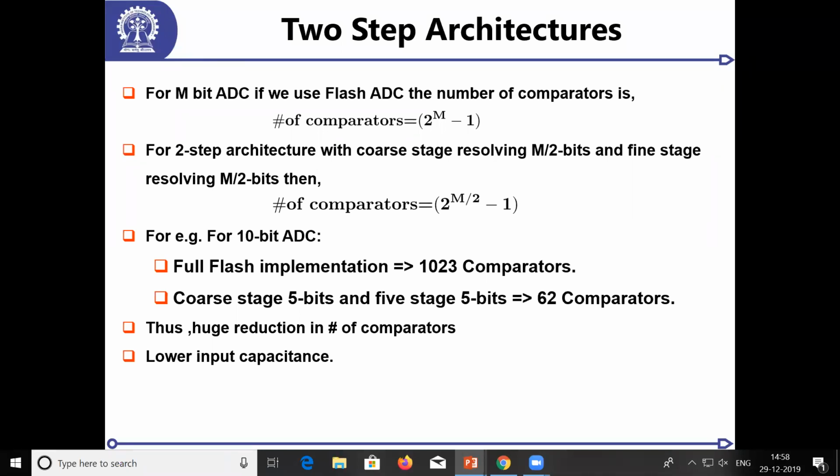Okay. Now this will be operating at a certain rate. Now this thing becomes something called a 2-input system. This is a nonlinear system, by the way, because of the quantizer. The quantizer is a nonlinear system. So this becomes a 2-input system. So what are the 2 inputs? One is the input V in, and the other is something called a quantization noise. Okay.